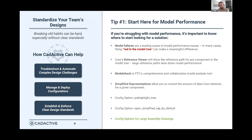One of the biggest things that separates Creo from the rest of the CAD landscape are simplified representations, and they're stored within the master assembly file, and they allow you to only load certain portions of the assembly that you need. For instance, if I want to load my model without any nuts and bolts in it, I don't need to see those things. I can do it, right? Please note that in order to modify a simplified rep, you've got to have the master assembly file in session, which is why we suggest managing these reps from a team level. And I'm going to stop talking. I'd love Ben to maybe give a little bit of extra background on some of the different types of simplified reps.